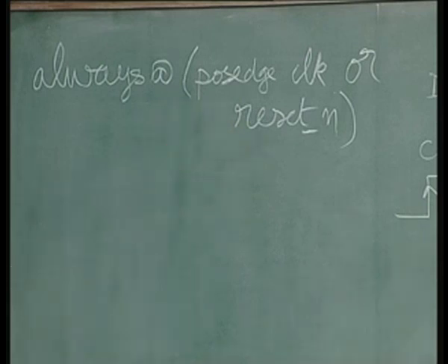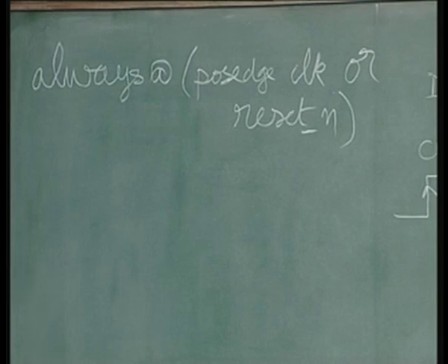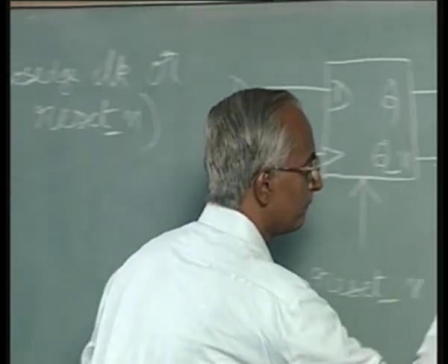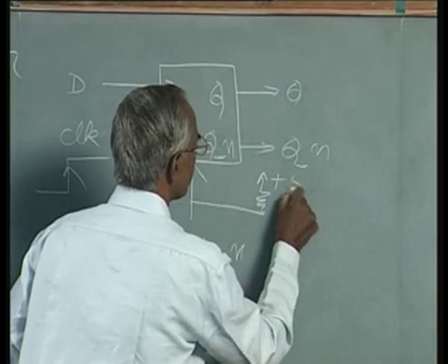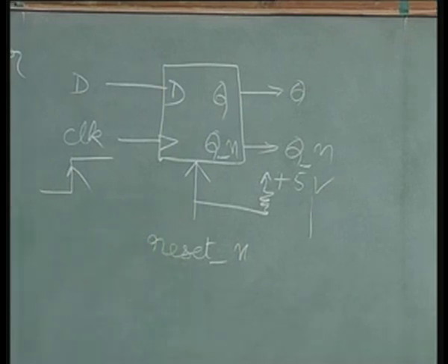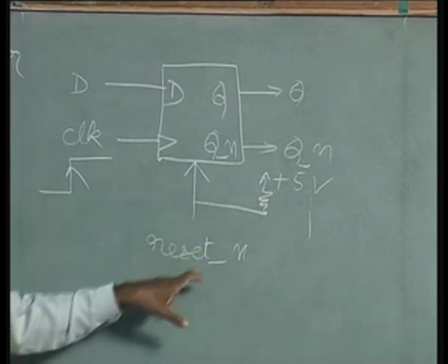And why should we go for reset underscore n being low? In bigger systems, this reset will be residing as a master reset on a control panel, and you need to reset from there, and that will be connected via a long cable in general. Suppose the cable snaps, it should return to a safe value. So in the circuit, where the reset push button ends in this PCB, you just put a pull up resistor. If it is plus 5 volt operation, this is the thing. So when a cable snaps, it takes to a safe value.